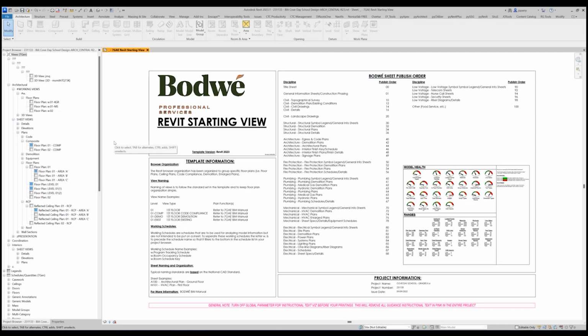The main reason I started doing it that way back in the day was that it was a pain in the rear end to try to keep that many families in a library. You had very limited server room and there are so many different options that you could have built into a door. You could have five side lights, two on each side, three on one side. You can have transoms, all that stuff. Well, that's something the curtain wall Revit tool does very well. So I've always built mine like that because that's kind of how they're built.